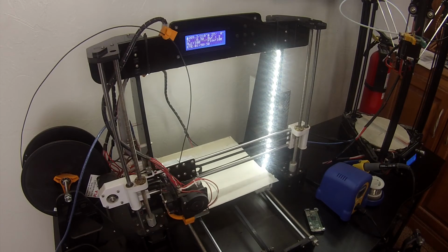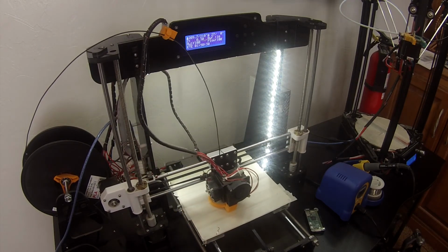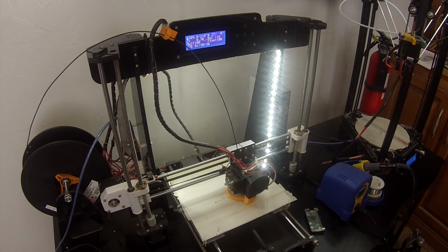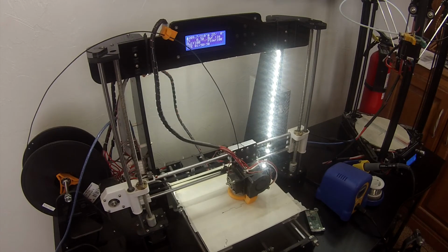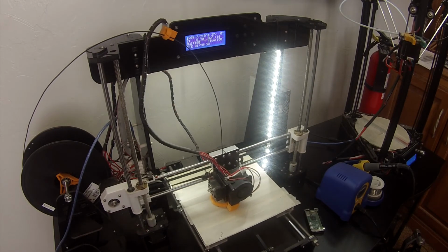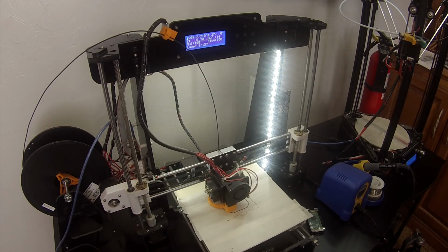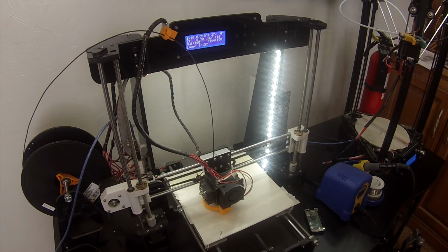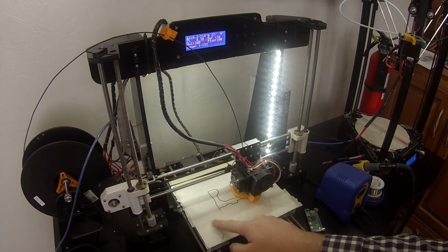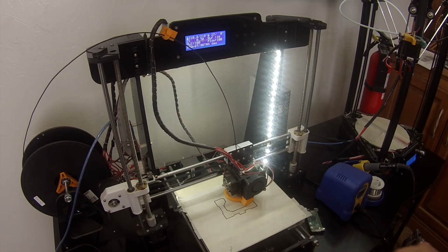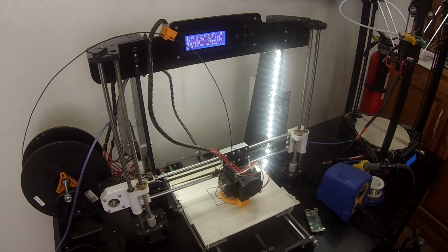So right now the machine is waiting to hit its ideal temperature, 210 degrees C, and it's off to the races. This bed has already been pre-leveled. In fact, if anything, with such a light trace for the first layer, I might have my bed a little bit too close to the nozzle. But you see now it's printing that outline we spoke about, and you see the print nozzle itself got rid of a glob at first, and it's improving the flow of the nozzle as it goes around.